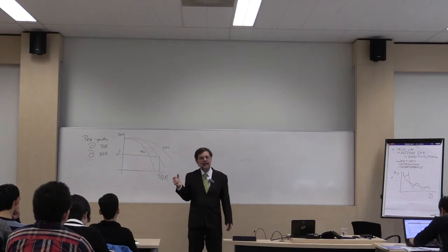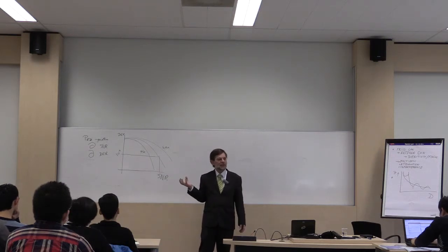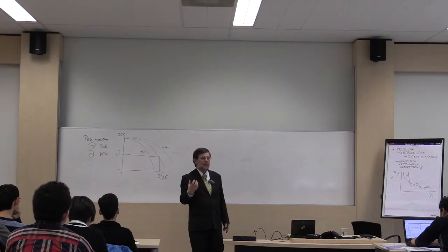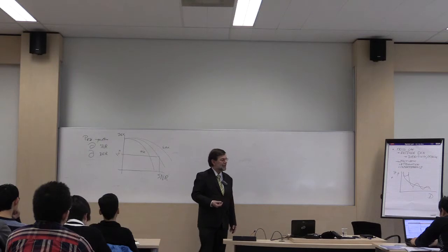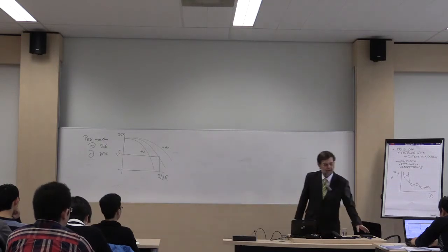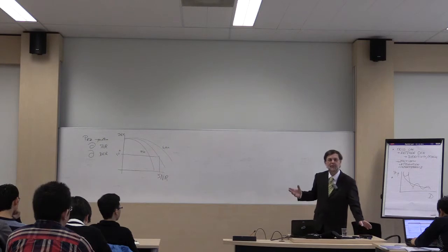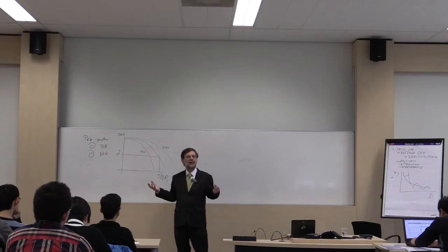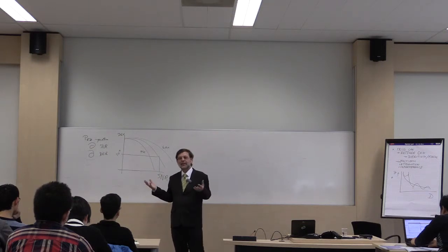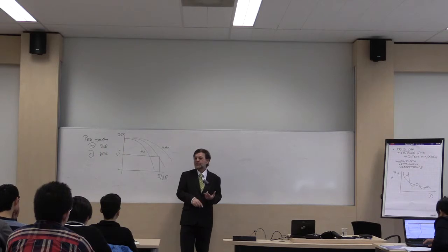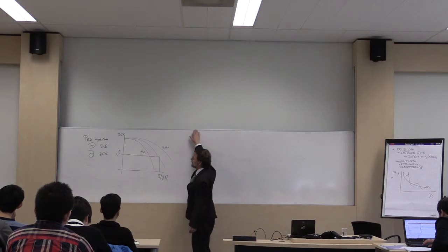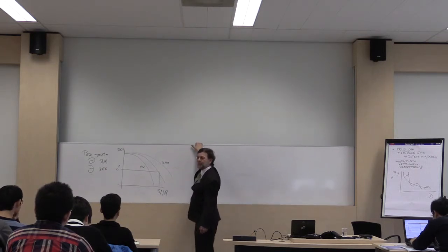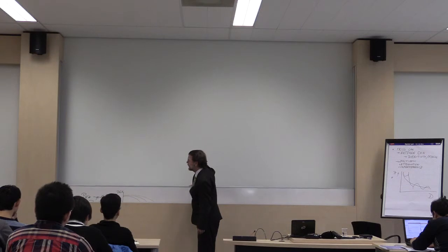That's also the reason why I didn't start using that in the first demonstration, because to understand what's happening with noise and with interference, it's much nicer to have an analog system like this radio, because you can actually hear the interference, you can actually hear the noise, and you can hear your signal. Whereas in a digital system, the only thing that you hear is, now there's sound, and it's perfect, and now there's nothing. And you don't know whether it's because of interference, or of noise, or of multipath, or anything. Nevertheless, personally I prefer digital quite a lot, because most of the time you have perfect reception.